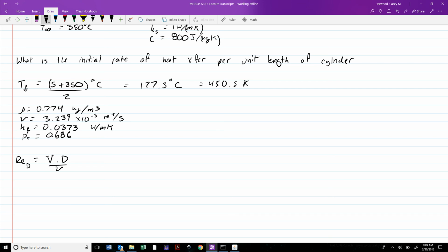I should remind you guys one more time, we discussed this last time, that in the flow around a circular cylinder or a sphere, we call the velocity of this flow way upstream capital V instead of U infinity, because U infinity is technically, when we get a boundary layer developing on this cylinder, there's going to be this velocity distribution. U infinity is the name we give to the velocity of the flow just outside the boundary layer.